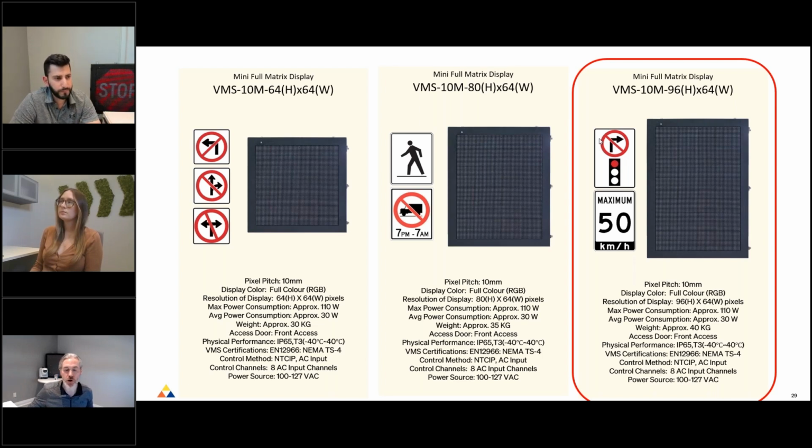And then for individual sign failures, what you'll notice between the two, I always call it the Lite-Brite versus a TV analogy. With an LED blankout sign, you have a big printed circuit board, and you insert these LEDs in a set, similar to a Lite-Brite, except you can't move them once they're in there. So an LED will fail, and you have to take the sign down, resolder in a new LED, and then reinstall the sign, or send it back to the manufacturer if you're not able to swap out LED components yourself.